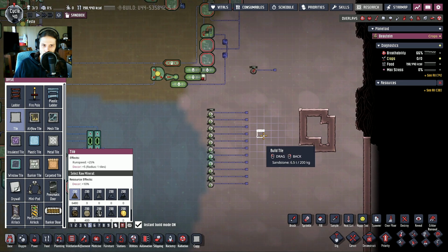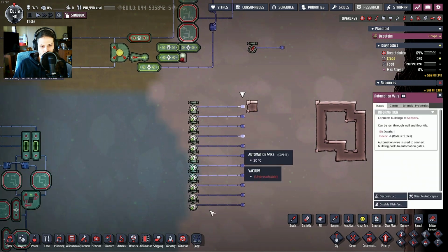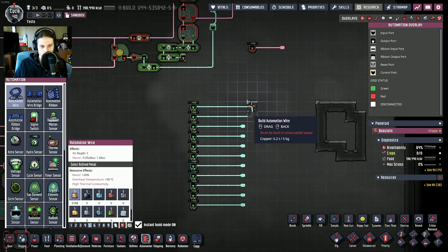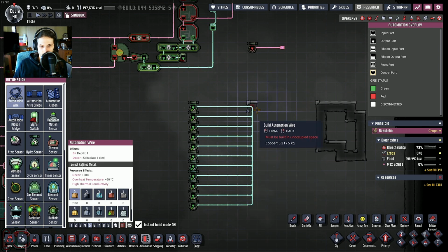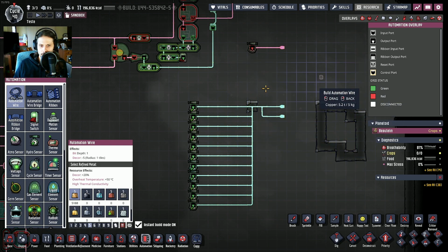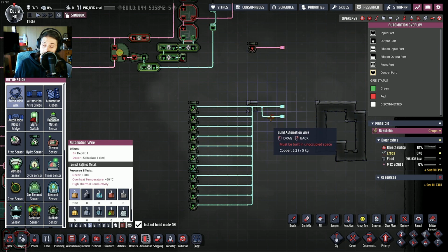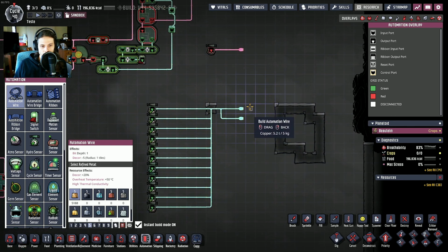What is this encoder unit? Well, pretty much all of your sensors are connected to this encoder unit, and this encoder unit will turn this analog signal that we have over here into digital, and that digital will then travel through two wires, which are usually twisted and with a wire mesh to protect from electromagnetic interference, right? And they will travel into the ECU.